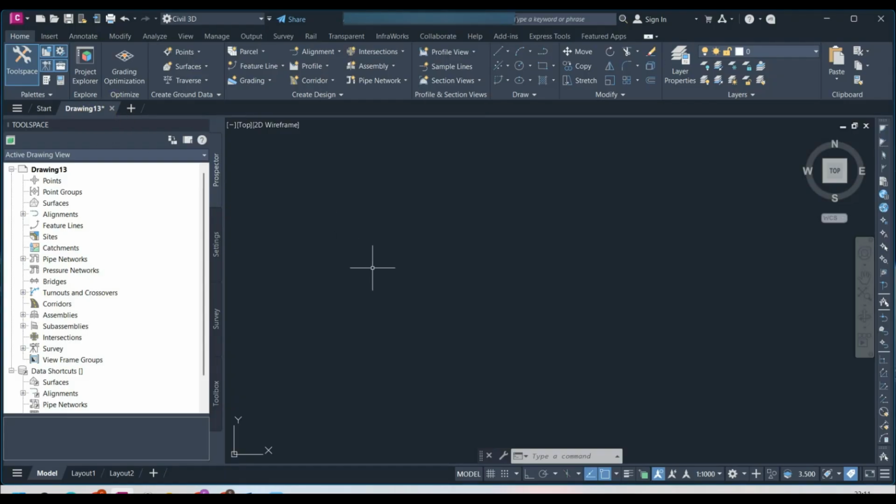Next, we will set the coordinate system of the newly opened drawing in Civil 3D. Why is a coordinate system necessary? As you know, once a drawing is completed, if we want to view it on a real map, for example, if our road project is finished, and we want to export it to Google Maps, Google Earth Pro, or Global Mapper and place it onto real terrain, we must first define the coordinate system of the drawing before we start drawing. To do this, we go to Drawing Utilities and then Drawing Settings.